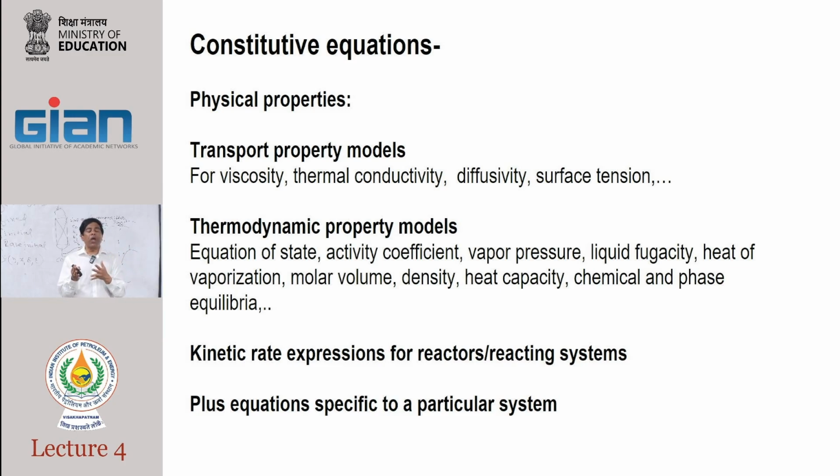So in absorption, we already know, okay, vapor liquid model, how do I represent the vapor liquid model? We have an activity coefficient model. There are only two models that we use, right, for vapor liquid equilibrium. Either it follows Raoult's law or it follows Henry's law. And then using the Raoult's or the Henry's law, we then write it in the form of an equation of state, or if it is some liquid that does not follow ideality, we use an activity coefficient model, and that's how we actually go for it.